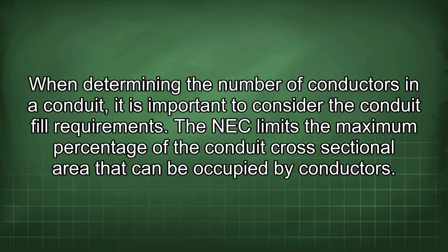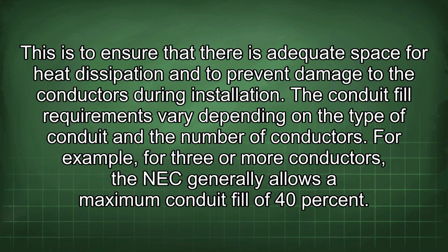When determining the number of conductors in a conduit, it is important to consider the conduit fill requirements. The NEC limits the maximum percentage of the conduit cross-sectional area that can be occupied by conductors. This is to ensure that there is adequate space for heat dissipation and to prevent damage to the conductors during installation. The conduit fill requirements vary depending on the type of conduit and the number of conductors.